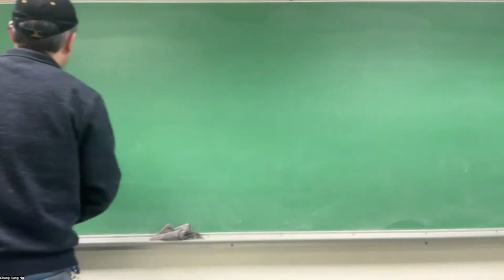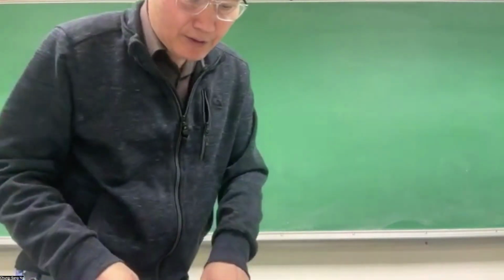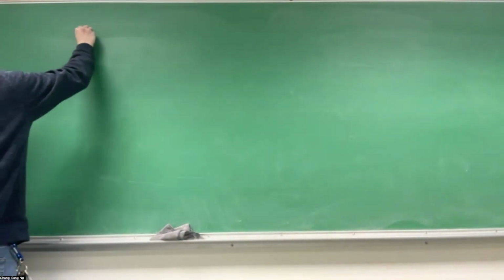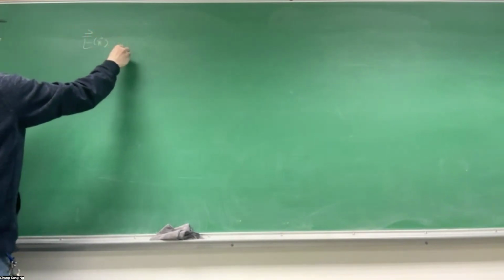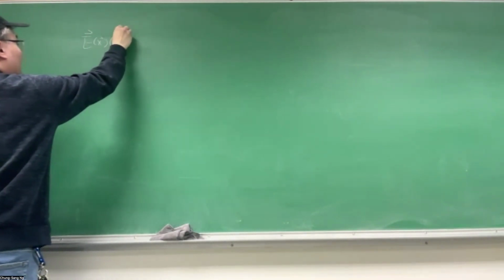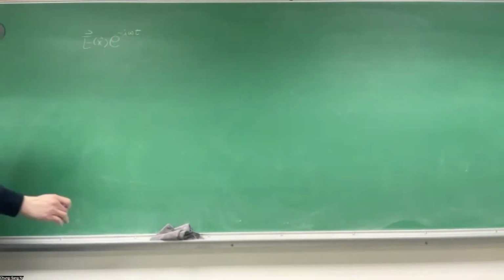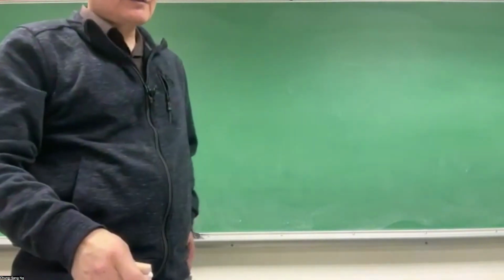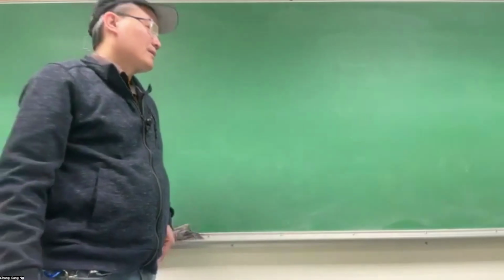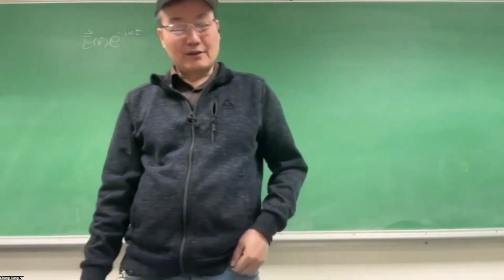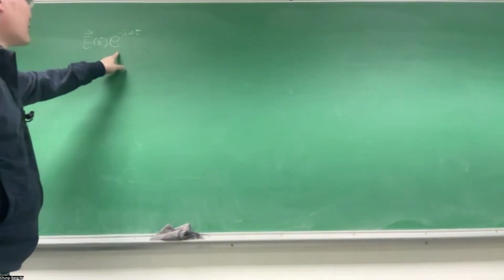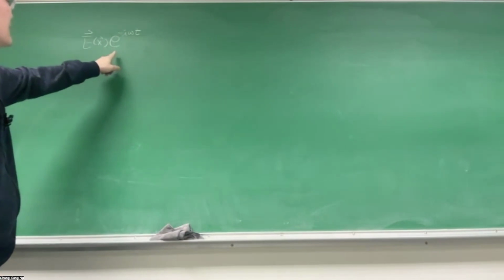So now everything is single frequency. The notation is like you have spatial dependence, like the electric field is spatially dependent, and then you have a single frequency, and it's much more convenient to use an exponential function for a single frequency quantity rather than sine and cosine. The reason is that the derivative of this thing gives you the function itself.